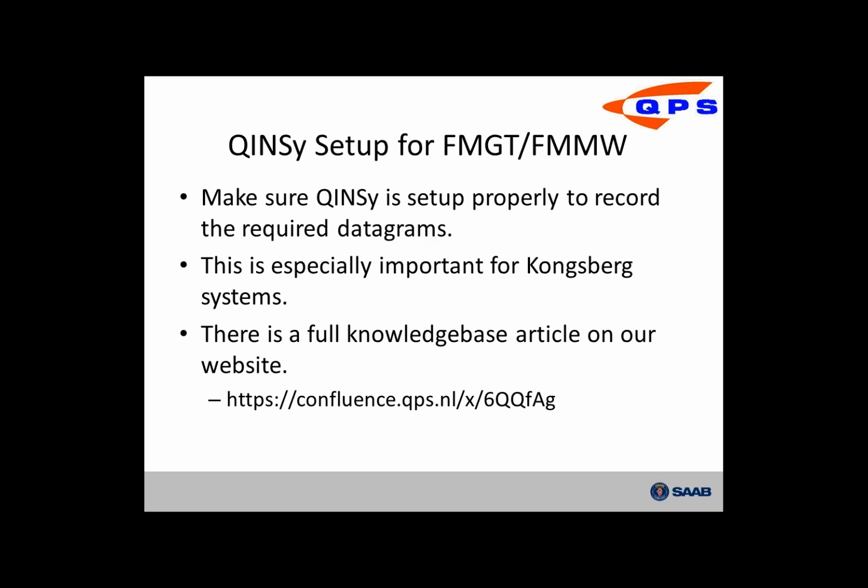It's really important that however confident you are with your setup in Quincy, before you go offshore and start recording a lot of data, you test the full workflow. Test your Quincy setup as soon as possible, record some data, and bring that into GT and Midwater, because that's the best way to ensure that what you set up is capturing the data you need to do the backscatter and Midwater processing. We really don't want you to spend time collecting data only to realize after the fact that things weren't set up properly to record that data.